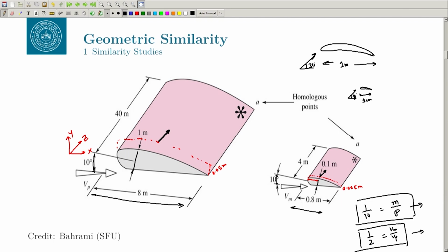For the kinematic similarity, it is very important that the flow should be in the same regime. Whether the flow is in the laminar, transitional, or turbulent regime matters a lot. The critical Reynolds number is the Reynolds number at which the flow transitions from laminar to transitional and then eventually to turbulent flow. If you are talking about a number in the transitional regime, it will be very difficult to correspond a prototype to a model unless the prototype is also in the same regime.